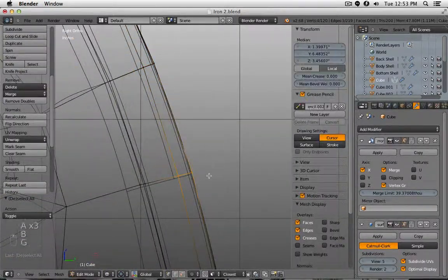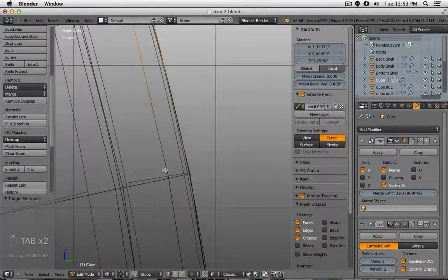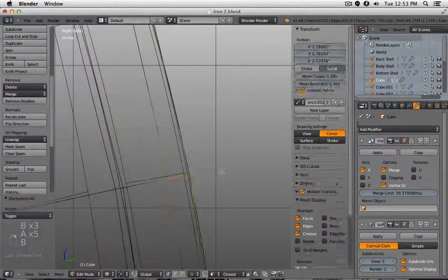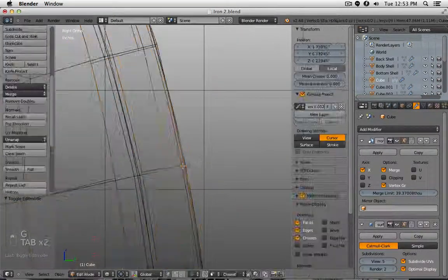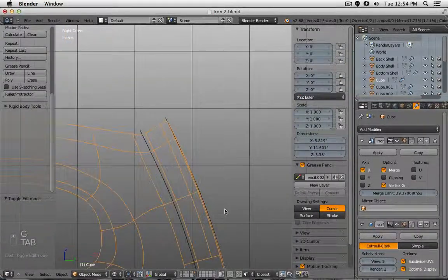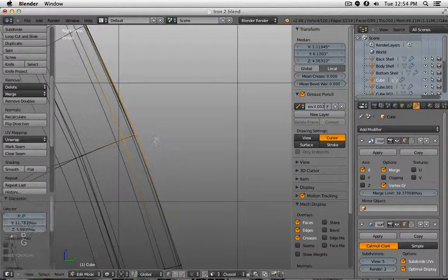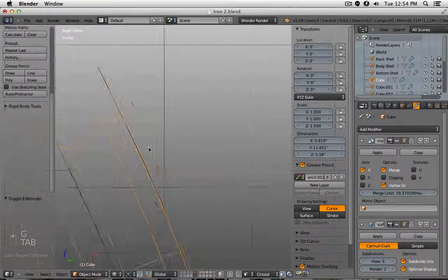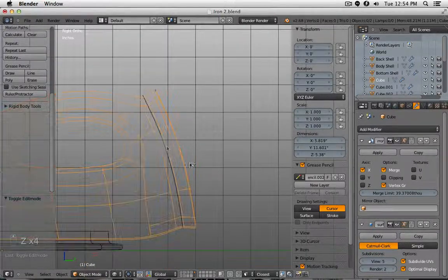But if, for example, you only have two lines to match, maybe the first approach is actually faster than this approach with the solidify modifier, because you have to do some other tests. But then if you have multiple points to correct, you can see I can just focus on fine-tuning my mesh, and I don't really have to adjust the reference geometry all the time.